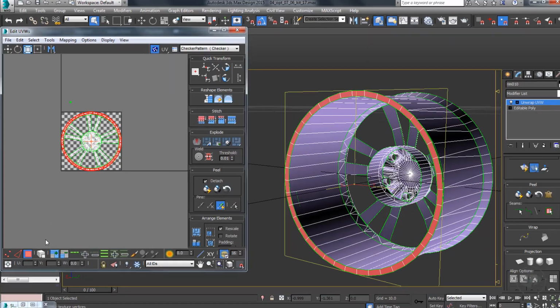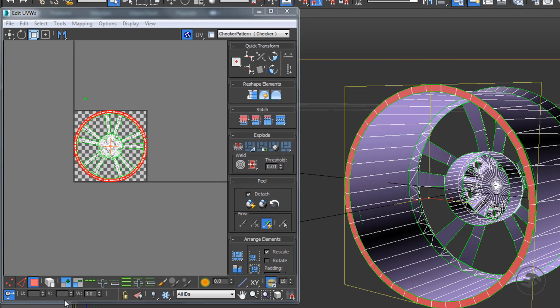numeric value in either the U input, which represents the x-axis, or the V input, which represents the y-axis. However, the W input is meant for procedural maps, according to Autodesk. Currently we are not creating any. By entering 1 in either the U or V input, the locator is going to move the selected UVs by one click, in relation to the selected UVs' location and the selected axis length of the checker box or the map.